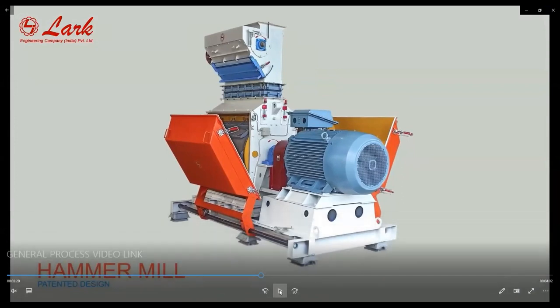The main feature a hammer mill should have is gap adjustment between the hammer tip and the screen, because for fine grinding we need less gap between the hammer tip and screen. For coarser grinding, we need more gap between the hammer and the screen. So there should be an optimum gap adjustment mechanism in the hammer mill to control the grinding process and to increase the efficiency of the hammer.